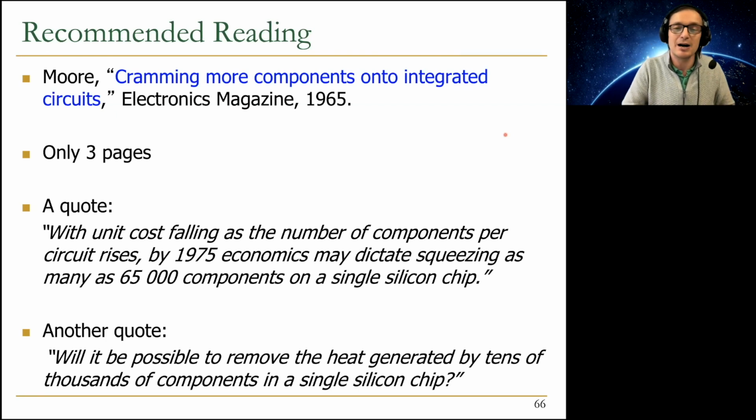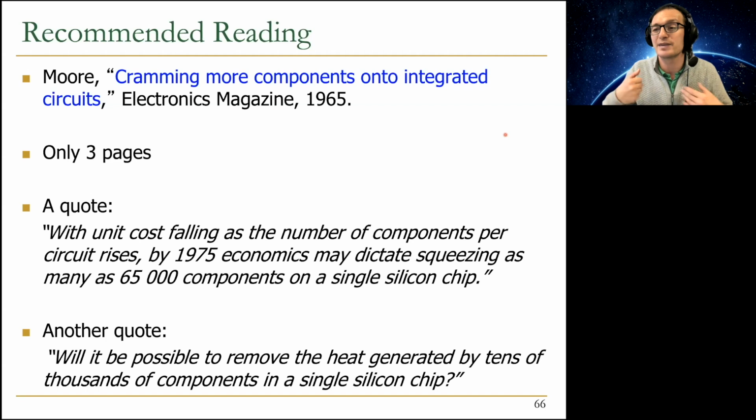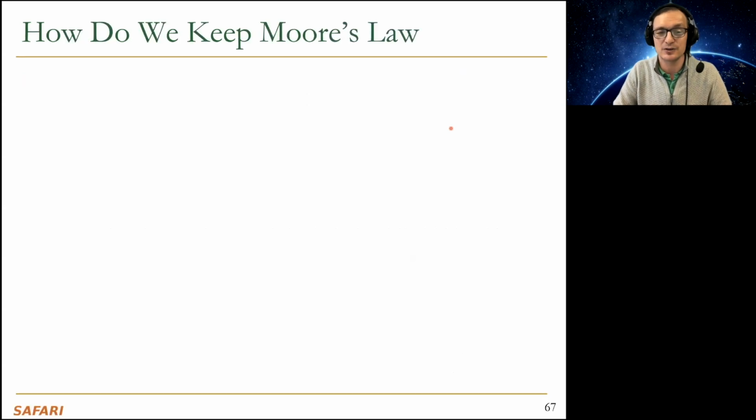Assuming we are able to power it up, at least a fraction of it, let's say, will these components switch at such a high rate that they will increase the temperature so quickly that they will have too much heat? And can we remove that heat as quickly as possible? And these are real design constraints in a chip. So thermal design power, for example, determines whether you can remove the heat with the cooling technologies that we have today, or that the chip is designed for.